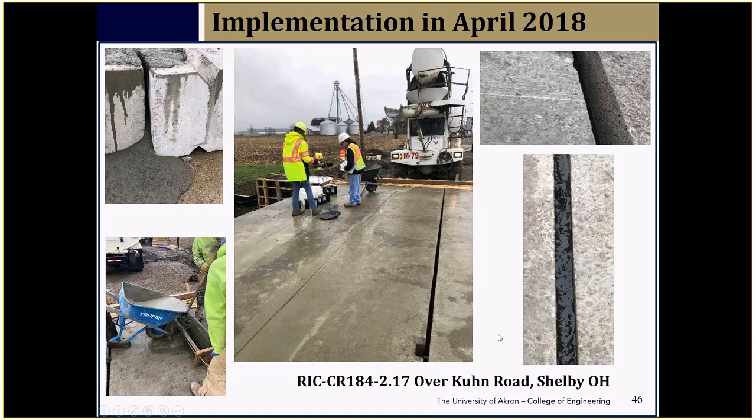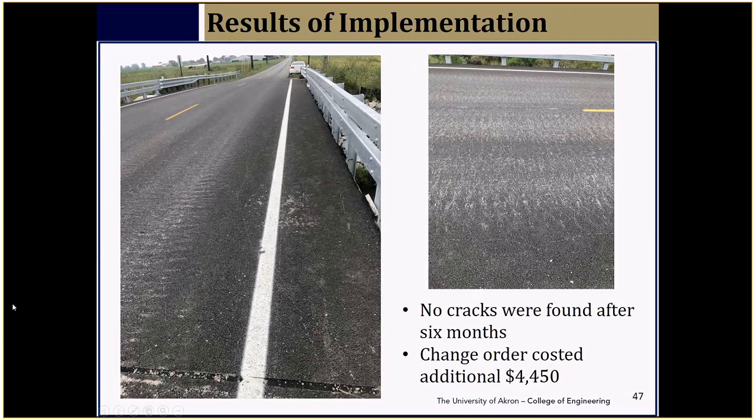They made this very flowable, which is not necessarily what we expected, but they did that with superplasticizer, which is good. It was flowing to the extent that when they were filling this joint, we can see that the grout was flowing to the far end and to the adjacent joint really well. So the constructability was tested very well.